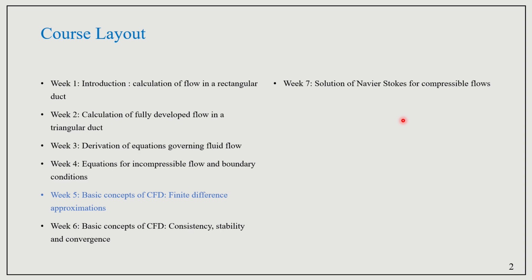So in today's class, it is about the finite difference approximation, concepts like forward difference, central difference, backward difference, and first order, second order, those things. And once we are familiar with these concepts, we will see how to solve the Navier-Stokes equations, because our ultimate aim is to solve those equations when we are dealing with fluid flow. So we can get an estimate of the fluid flow variables like velocity, pressure, and if any energy exchange is taking place, we also get to know the temperature at that point.